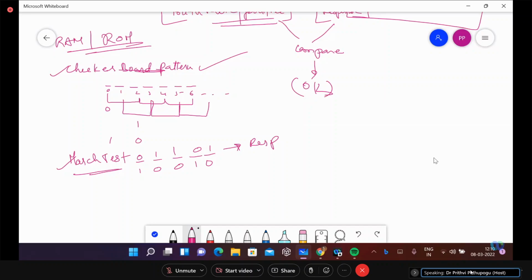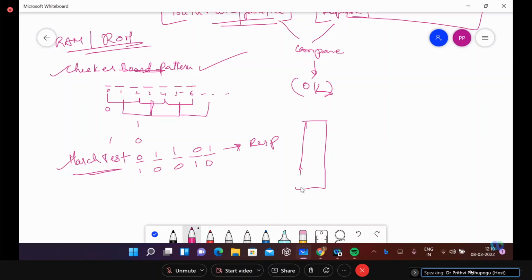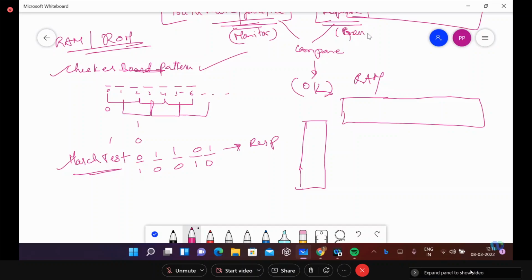Okay, when we are giving these inputs, what is the setup, or the way these RAMs and ROMs are getting tested? I said no, here the response is collected, and that response will be compared with the fault-free response. So this we call the monitoring segment. So this is what you say response generator. Okay, so both will be compared.